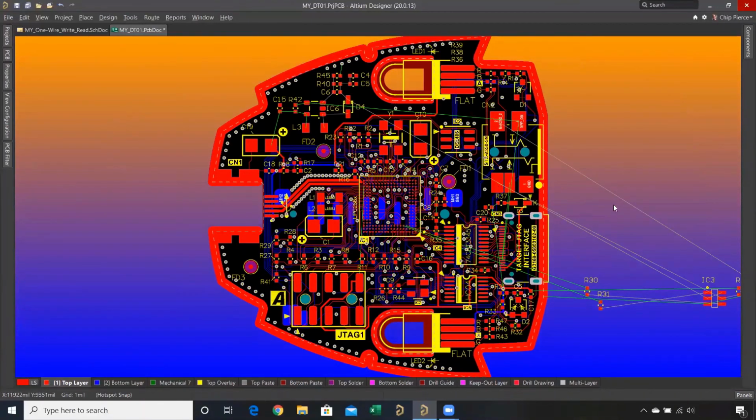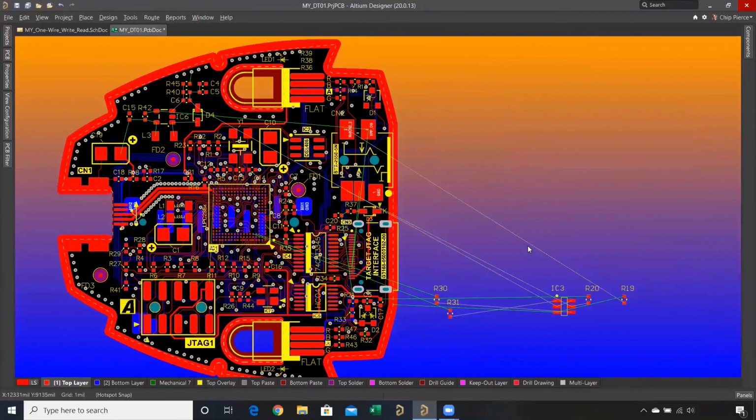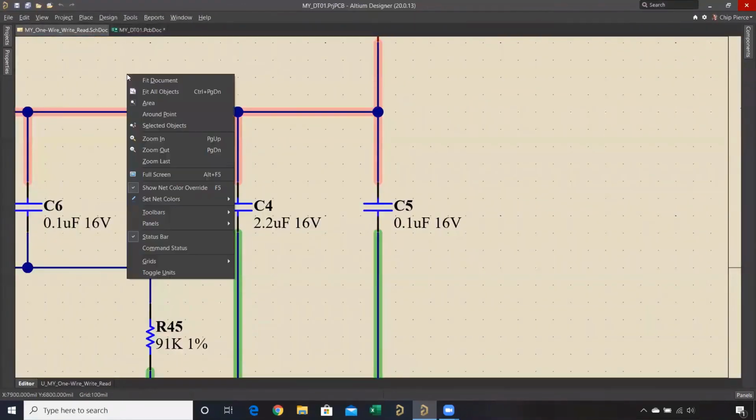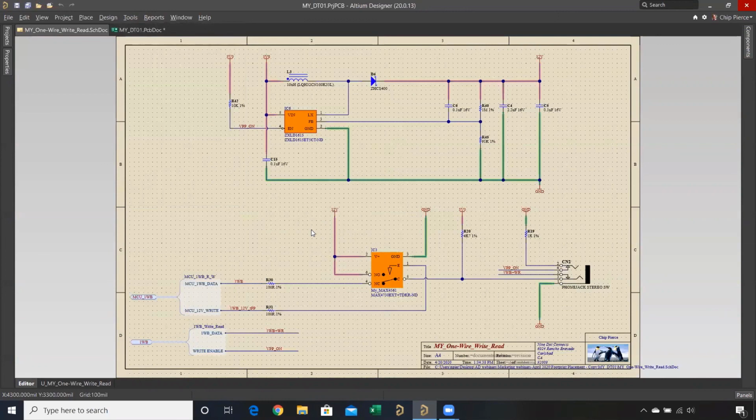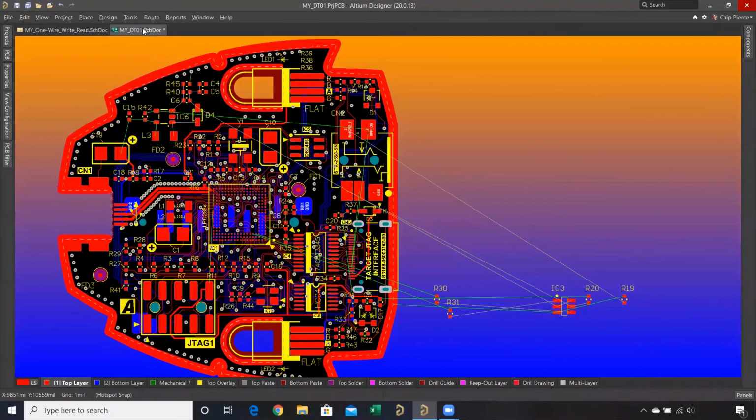And of course you can see I've got some other footprints off to the side here, and I'd use those same placement techniques, rotating the components properly to straighten out those connection lines. And that's what it's all about, folks, placing components on the PCB. You can use some of these commands like cross probe and cross select mode, which I leave enabled all the time. Cross select mode's really helpful. So we've got some of these semi-automated tools to reposition the selected components as well.